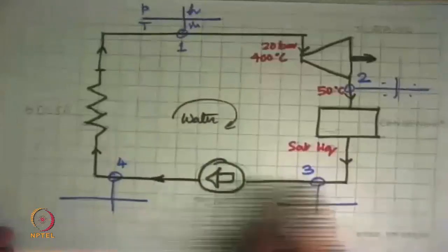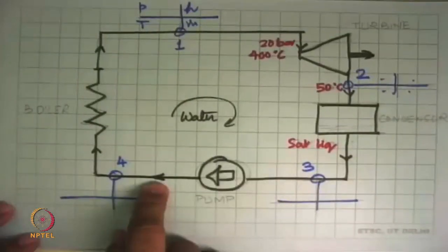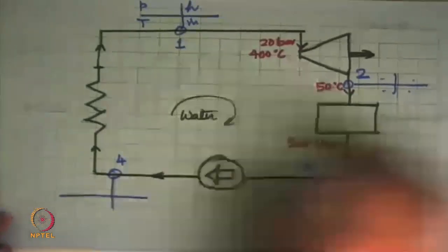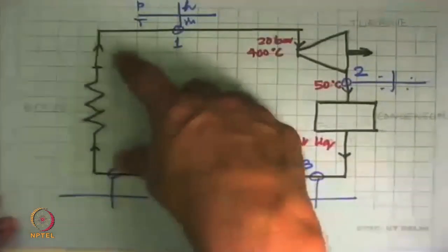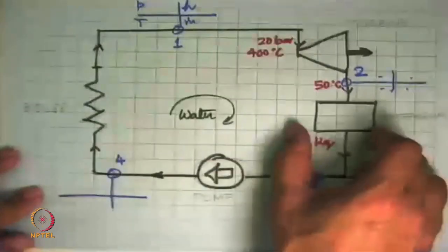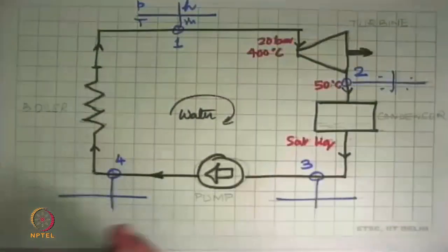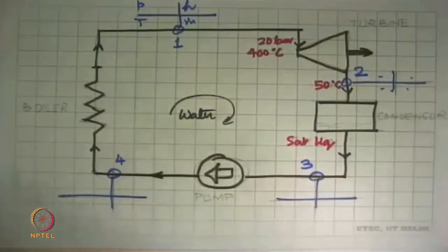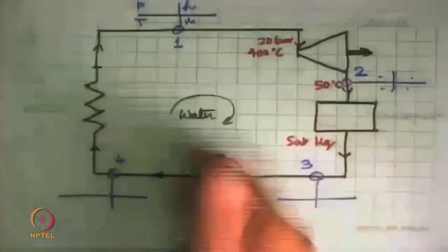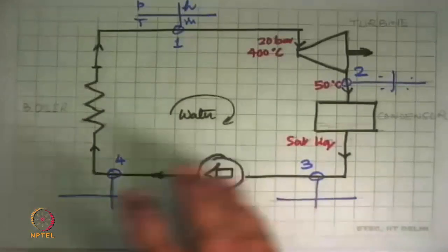And so we say, I need so much mass flow rate, I'll give some margin on it. I need this as the inlet pressure, this as the outlet pressure. Which are the pumps that I should buy? This will tell us the flow rate and the inlet and outlet conditions, which is the boiler that one should buy. Same thing with the condenser, same thing with the turbine. So these are the beginning of the designing and then finally putting together of a system like this one. Real systems will have more components than this, but the process that I have just mentioned is the same for all of these.